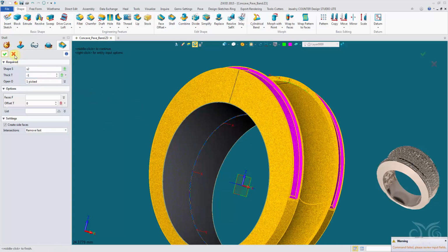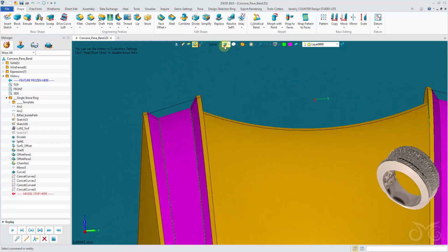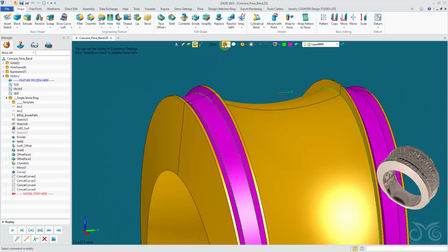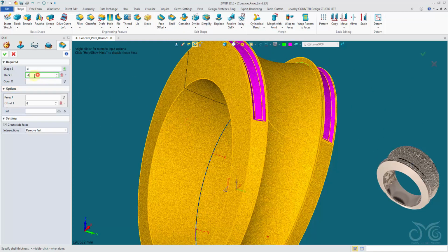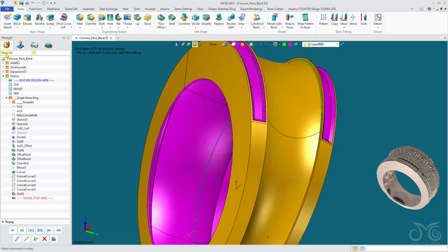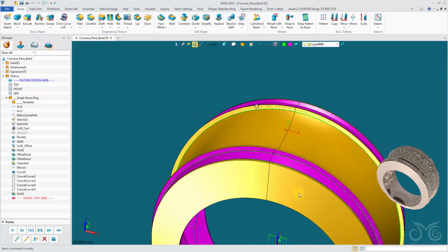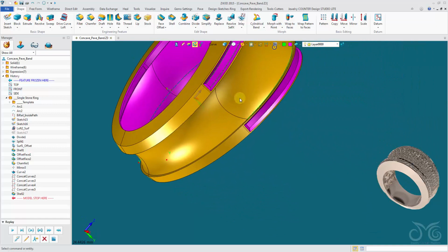And it fails, and the reason it fails is because our ring shank sketches are slightly more complicated. We can't shell, say, our wool here, because we'll be forming self-intersecting surfaces. I'm sure we could get away with a shell if we had a very small number, say -0.2 millimeters. Our shell is working then. However, we cannot have our ring this thin. So we need to come in with a different strategy to shell out our ring shank.